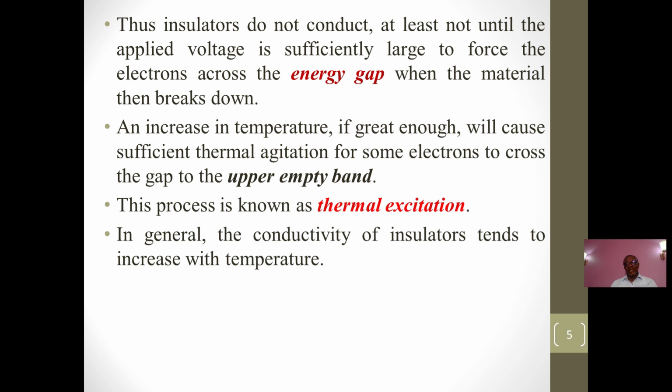What we are saying here is that even though some materials are called insulators, and you use them to cover conductors, if you apply sufficient energy or heat, then at a certain point those insulators will break down and become conductors. It is important for us to note this because the Zener diodes make use of this principle.